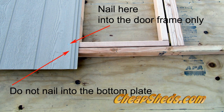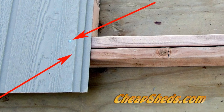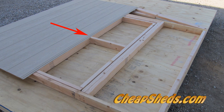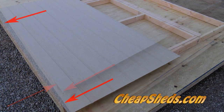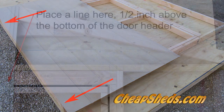Put a nail through the siding into the inner door frame bottom cross piece about 2 inches from the edge of the siding, but do not nail into the bottom plate because doing so will nail the door shut. Put another nail in the center door cross piece and the top door cross piece, and then in the top plate. Double check the overhang measurement at the outside edge of the bottom plate and put a nail at the outside ends of the top and bottom plates.